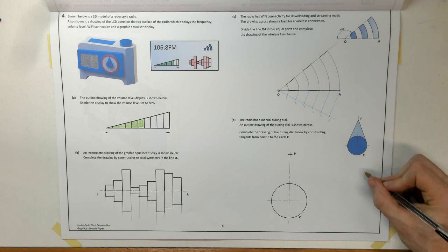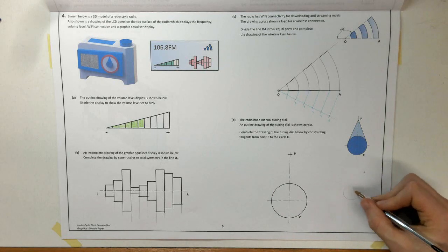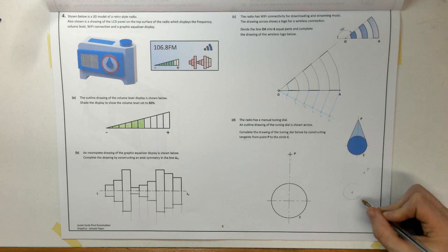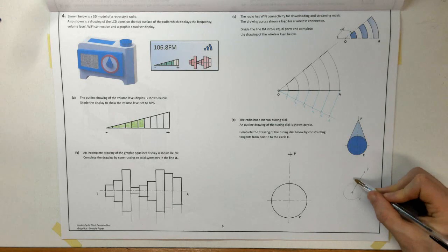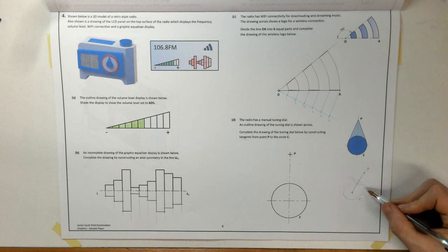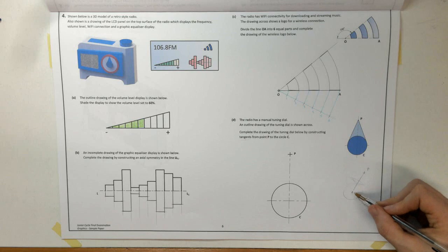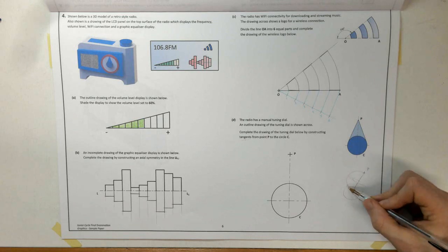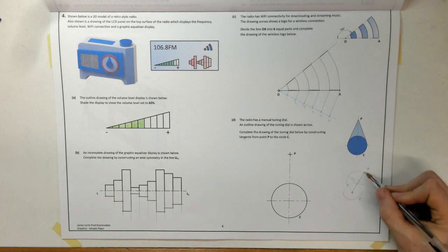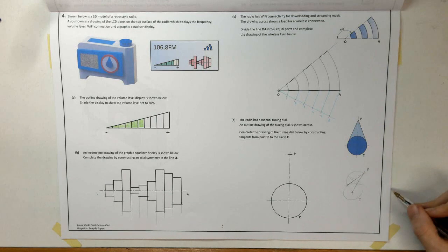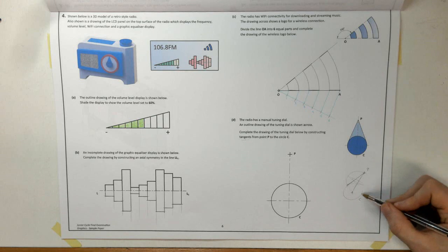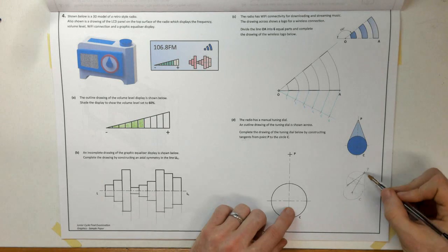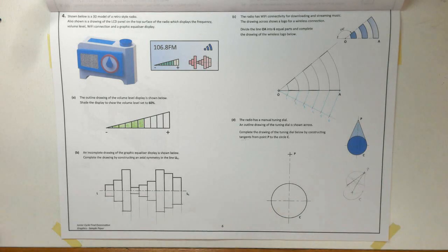So the construction for this is usually I'll just draw a random circle and a point P. Here's my circle C, point P. So what we do is we join the center back to P. We bisect that line, and we draw a semicircle in. And where the semicircle intersects the circle, that will be my tangent. And because we want a tangent on both sides, we'll draw a full circle, and that will find it on both sides.